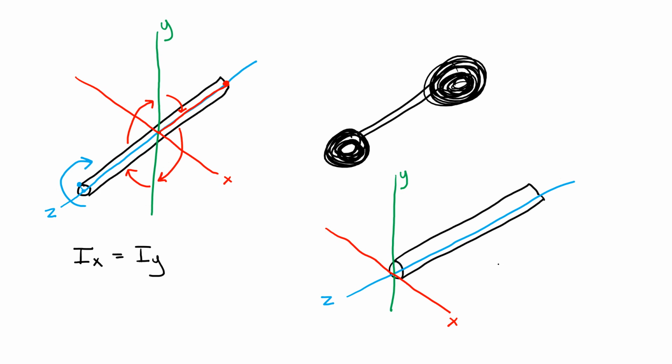You can see in this example that the moment of inertia in z is going to be the same as it was in the first case. However, the moment of inertia in x is going to be much greater than it was in the first case over here, because the distribution of mass is now at a very long point away from the pivot point.